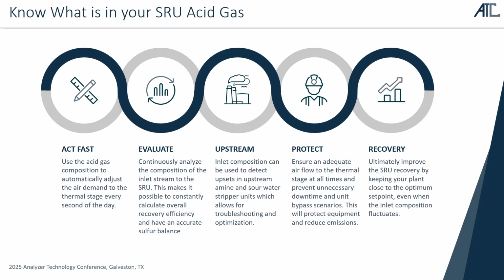But depending on where we have some space to put it, create some residence time to do that. And in order to combine it all together, basically we have something that real-time sets the air demand of the plant based on the composition of the gas coming in, basically every minute of the day, every second of the day.